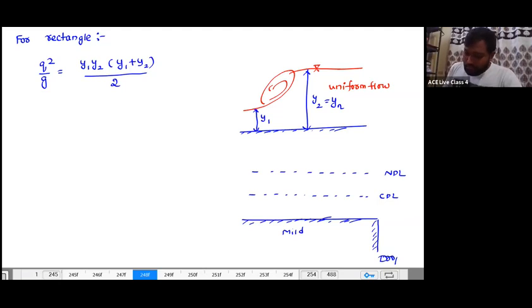So now the flow below the sluice gate, on the downstream side, is going to be supercritical, and there is a hydraulic jump, and the flow meets the uniform flow. Immediately you observe over here, due to the drop, the water level will fall like this. Yes or no? Water level will fall like this.